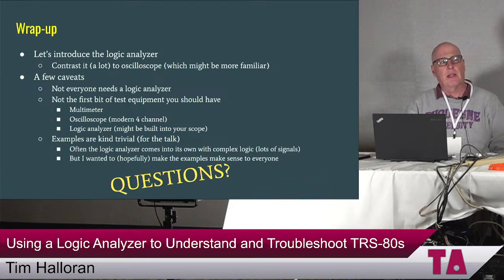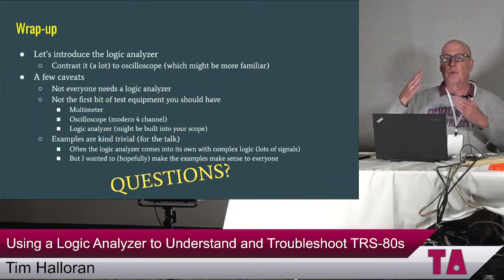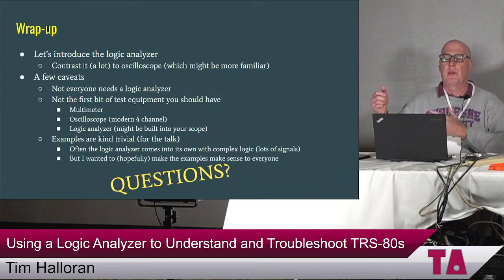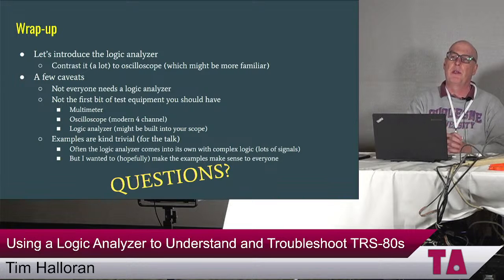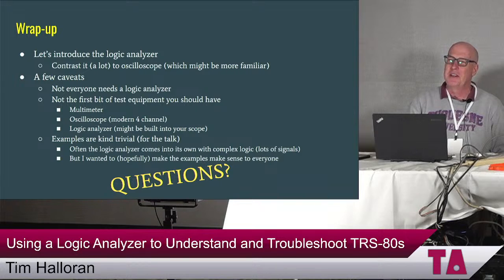I've used it. In fact, last year, if you remember, my demo was showing TRS-80 going through real serial ports to real terminals. I used both of these logic analyzers quite a bit, sometimes both at the same time, hooked up to two serial lines decoding the RS-232 to see what was going on. So they can be useful for that. And that's super slow, you don't need anything super sophisticated for that kind of stuff. Certainly not something the Bus Pirate would do very well.